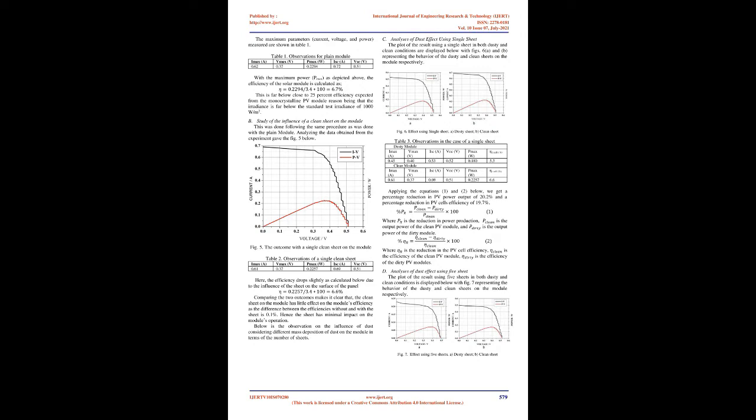Dust samples collection. To study the effect of dust, topsoils developed on basaltic rocks representing different stages of soil development were sampled from 4 sites, which are Buea Town, Maliko, University of Buea Campus, and Buea. These soil samples were collected from the soil horizons up to a depth of 50 centimeters. The samples were air-dried for over 3 days and stored in plastic bags. Roots and litter were removed and samples lightly crushed with fingers to loosen soil aggregates and remove rocks.